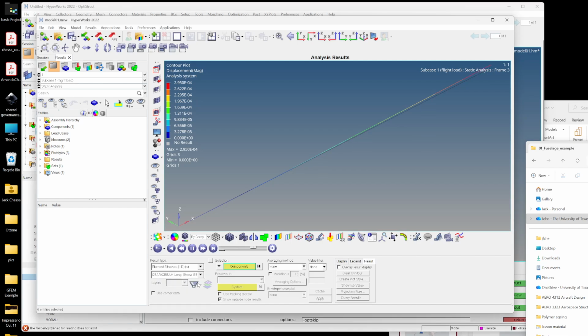Here, we're just going to see the bending stresses, and then again you can see the max and the min bending stresses, all right? So if we pick axial and apply, you can see we're seeing the combination of those two. If we pick the bending one, we'll just see the bending stresses. There they are. Right, so there you go.